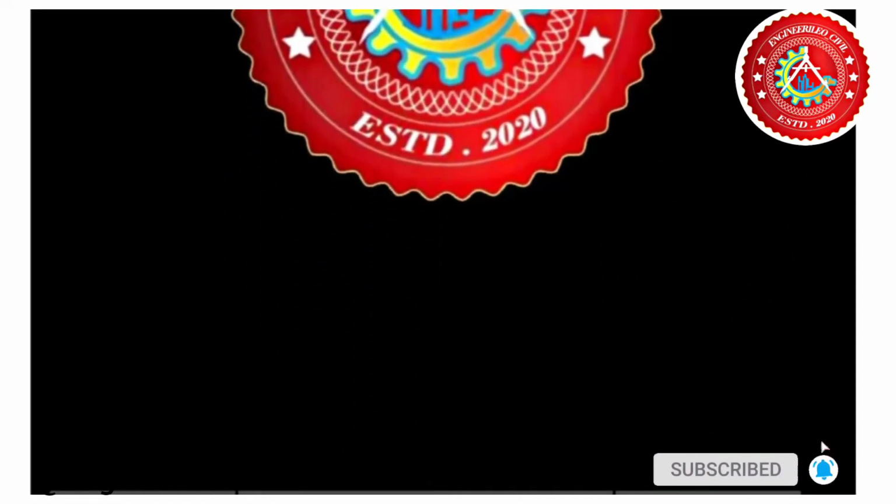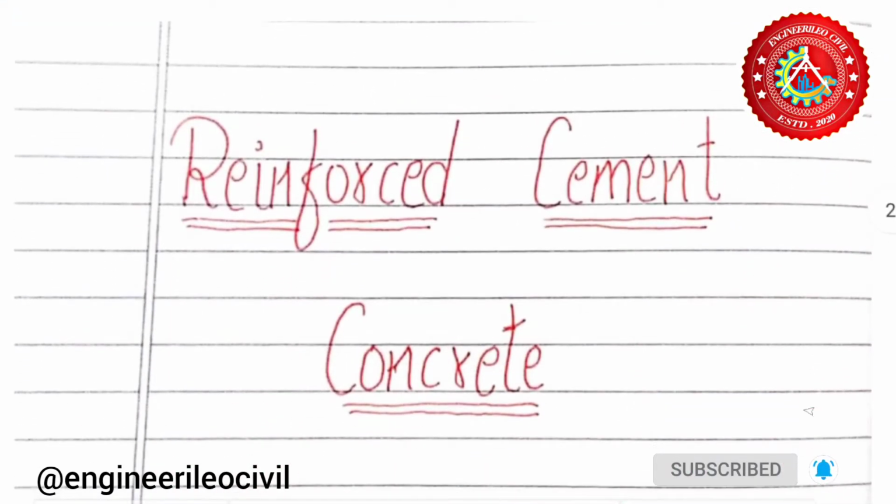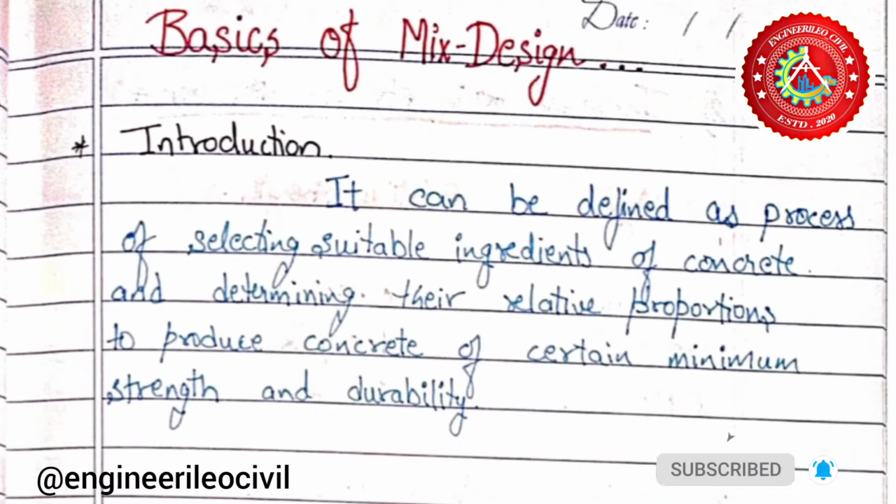Today we are going to learn various topics which include the introduction of mix design, methods of proportioning of concrete mixes, grades of concrete, compressive strength of concrete in structures, and mixing, compacting, and curing of concrete. So guys, let's start with our introduction. First, let me define it. It is defined as the process of selecting suitable ingredients of concrete and determining their relative proportions to produce concrete of certain minimum strength and durability.